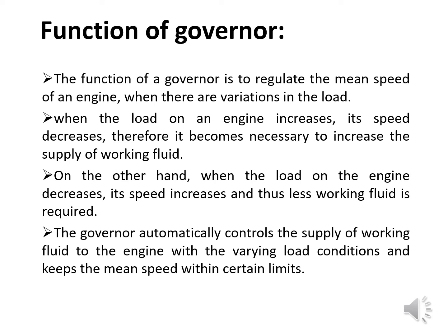On the other hand, when the load on the engine decreases, its speed increases and thus less working fluid is required. So the governor automatically controls the supply of working fluid to the engine with the varying load conditions and keeps the mean speed within certain limits.